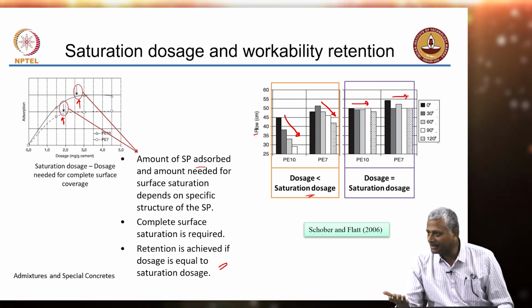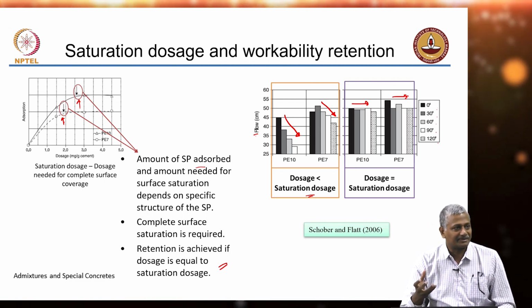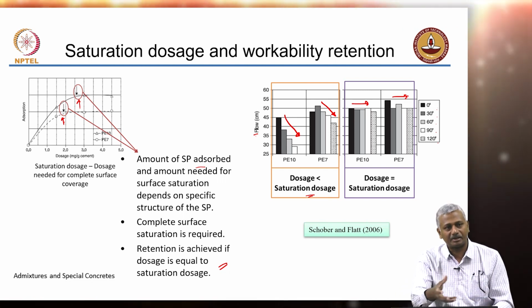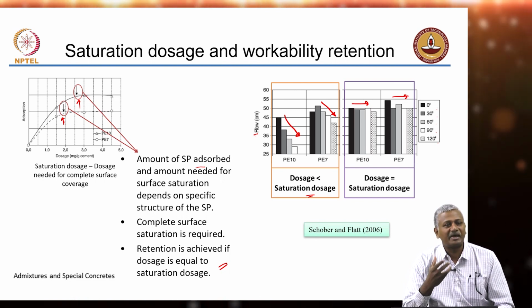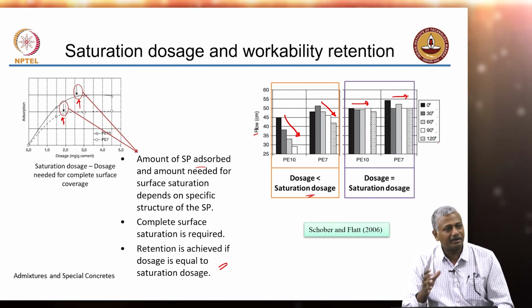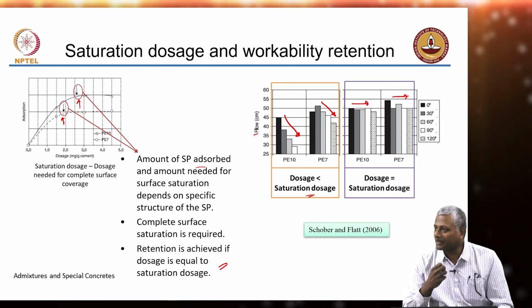When I went there on the third day, I could actually still feel the concrete not fully set. It had not hardened. They had cleaned up mostly, but I could see some samples lying down. I could also smell the admixture very clearly. Sulfonated naphthalene formaldehyde has a very clear-cut smell, right? So, you could smell the admixture.